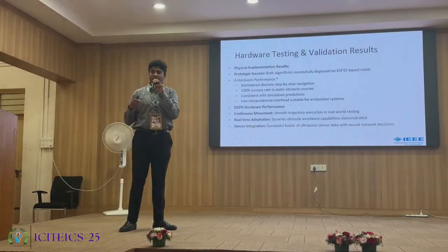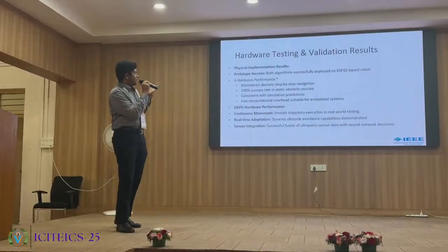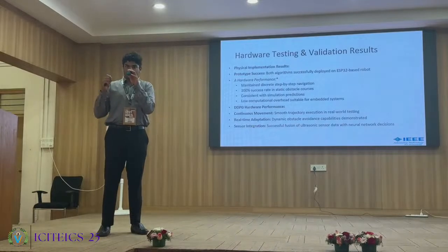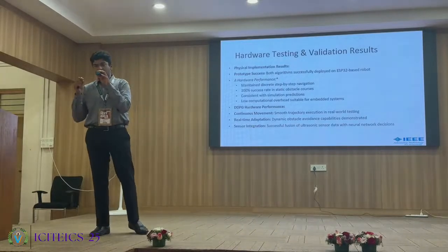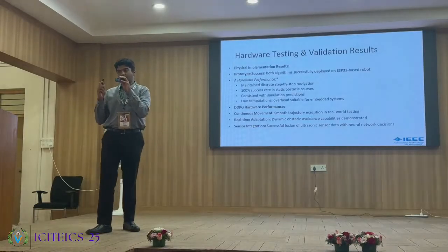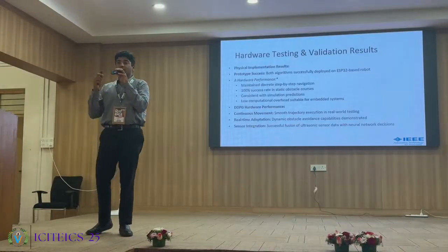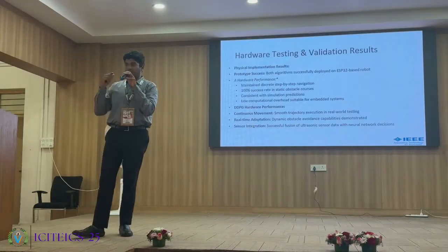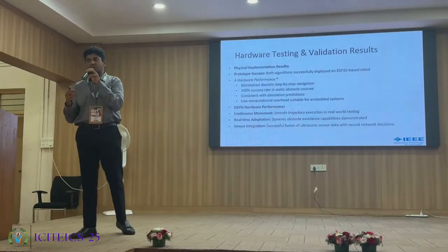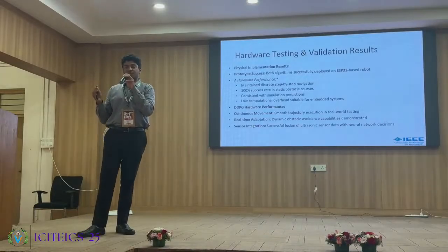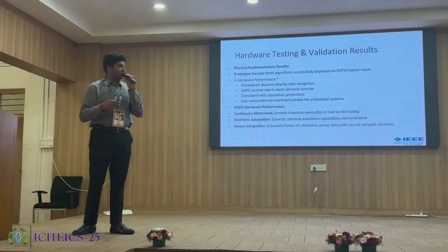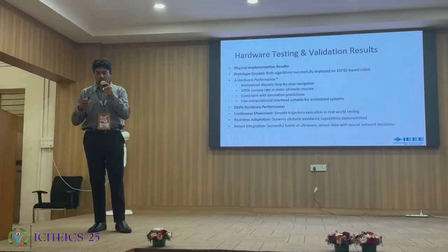Step by step we were able to implement and also validate the results by hardware implementation, and we observed that the discrete movements provided by the A-star algorithm are successful in every case, but when it comes to real-time and smooth operation, the deep deterministic policy gradient model is better because it was able to provide continuous motion rather than discrete motion. But the computation and training is more time-consuming as compared to the A-star algorithm. That is the comparison we were able to understand, and both these methods have their own pros and cons, and depending on our application, we'll be able to choose.